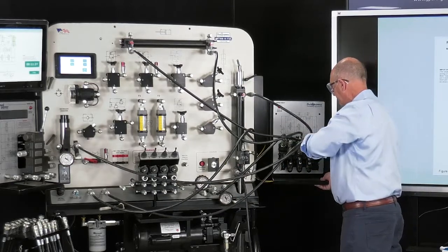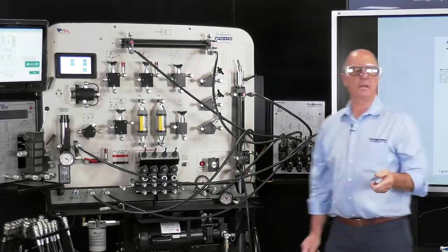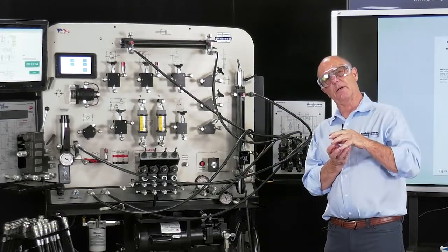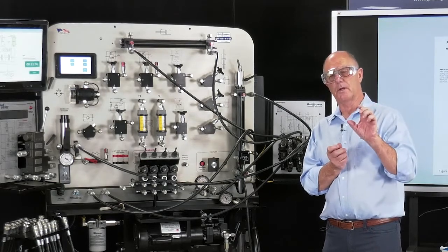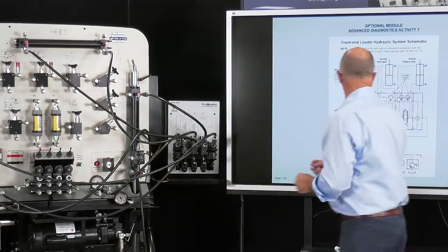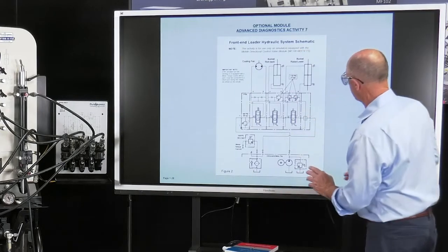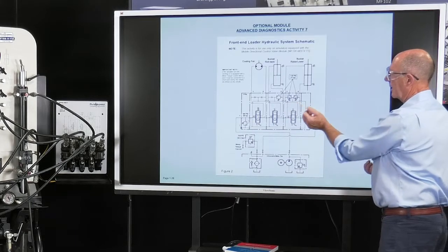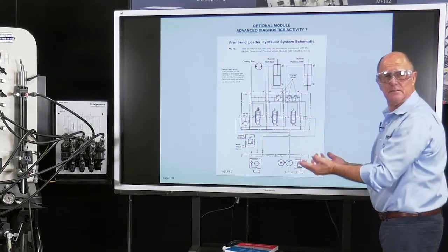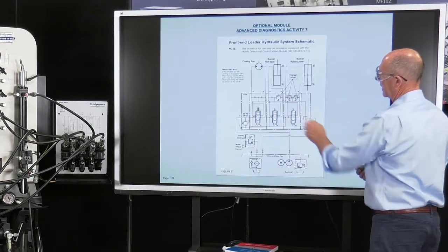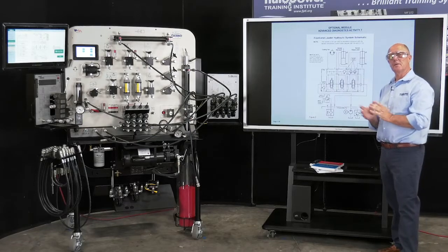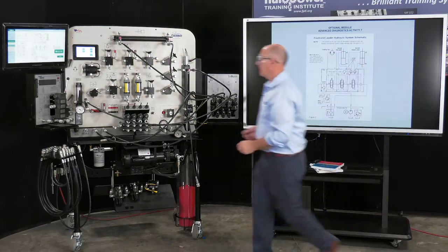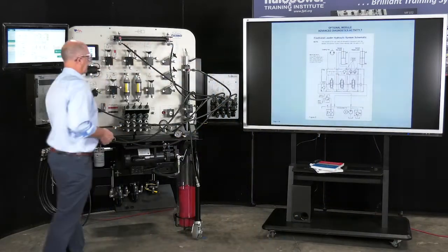Now, interestingly, in a directional control valve, when you are microleak testing it, you're testing everything in that port. So right now, looking at the schematic, I'm testing to see if it's leaking in the cartridge, the cylinder port, relief valve, anti-cavitation valve. I'm looking at the seals, and I'm looking at it to see if it's leaking across the spool bore wear. I'm looking at all of that. Let's see if it passes the test. So I'm going to run the test now on a microleak into that B port.